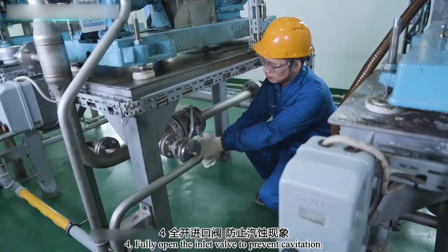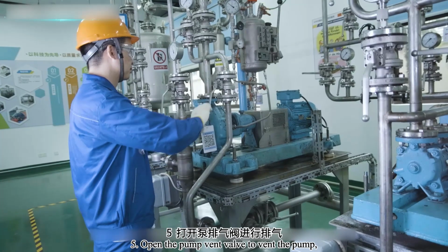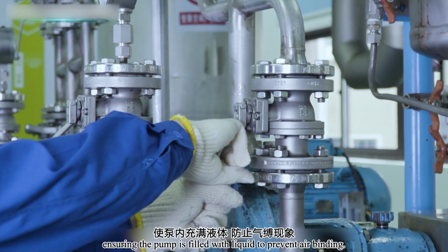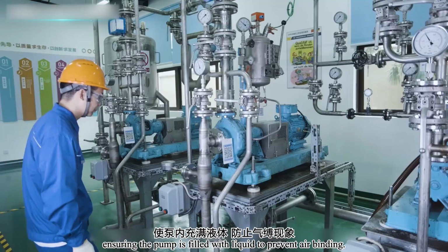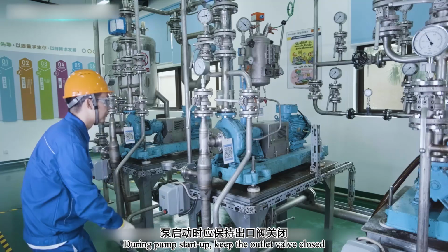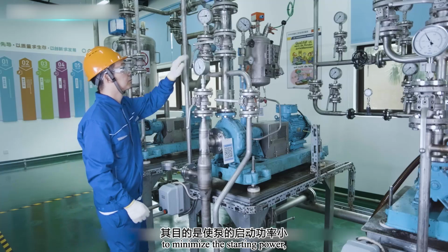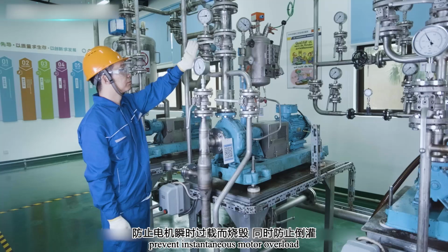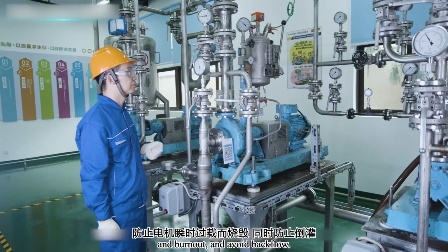Fourth, fully open the inlet valve to prevent cavitation. Fifth, open the pump vent valve to vent the pump, ensuring the pump is filled with liquid to prevent air binding. Sixth, start the motor. During pump startup, keep the outlet valve closed to minimize the starting power, reduce the motor starting current, prevent instantaneous motor overload and burnout, and avoid backflow.